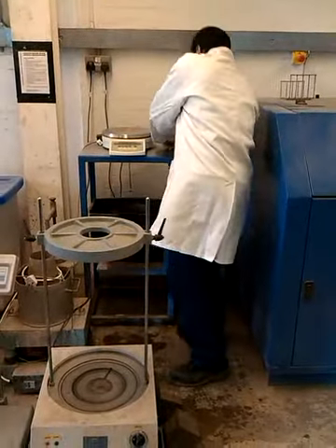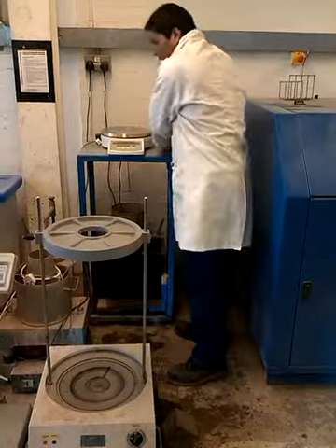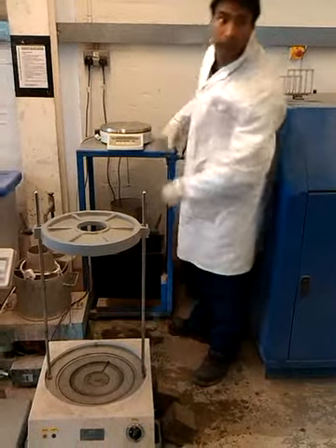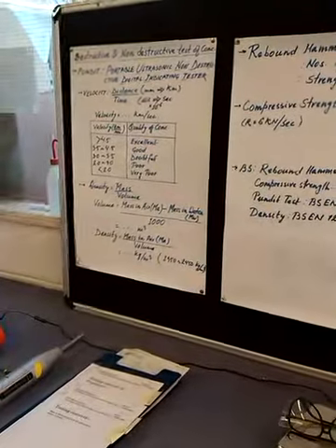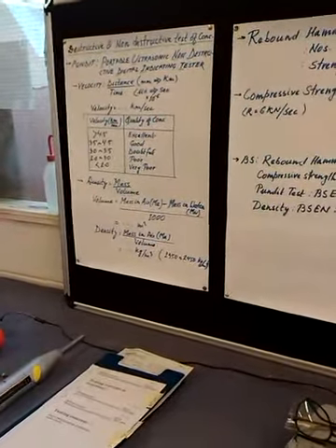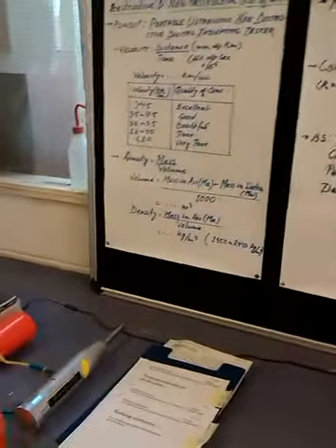So we got both readings, mass in air and mass in water. I hope we can now calculate the density. Right? Any questions so far for the density calculations? No. Right. Now the next step is to find out the strength of the concrete using the destructive way.